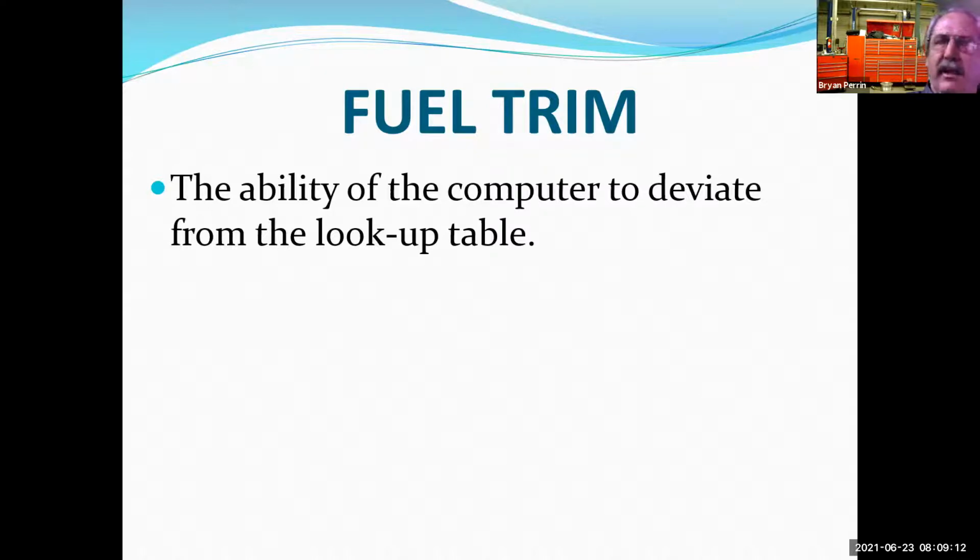But in reality, we may not be adding more fuel than what was originally required, because we may have low pressure, we may have a plugged injector, we may have other issues going on. So the computer's intent is to add more fuel, but we might not be adding fuel above what was originally required. We may just be getting back to even based on other issues.